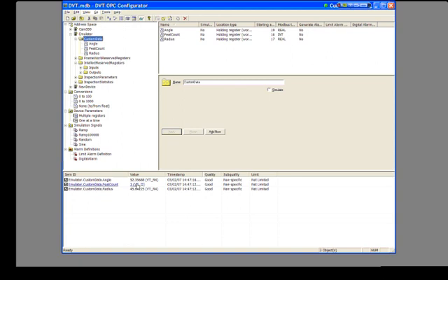There we go. It took a while to set up, but now we're seeing all the values that we see on Intellect. And as we trigger different inspections, we will see these values change. One thing I wanted to mention again is that monitor view is only for monitoring purposes. Any OPC client will of course be able to both read and write to these values.